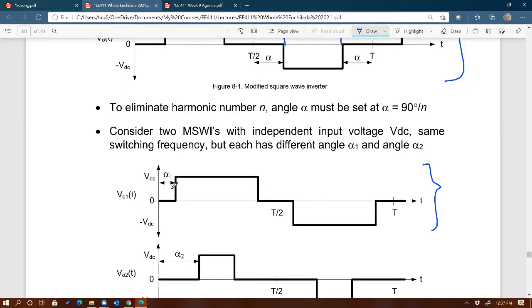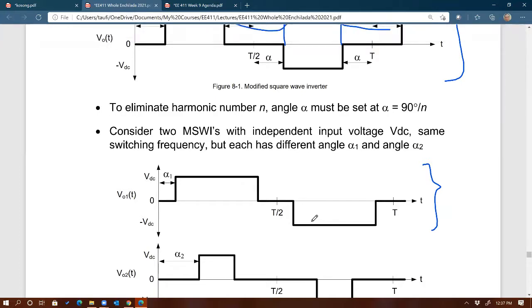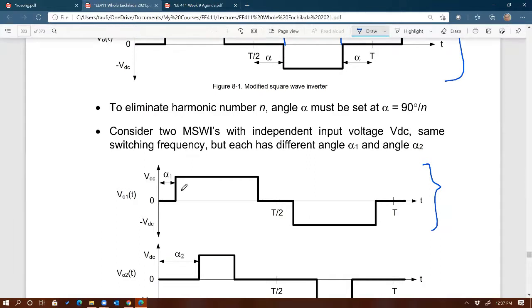Imagine if the applied voltage looks like this, then you have some kind of spinning of the motor shaft that is not smooth, because of this shape. What do you call it? Like cogging, maybe, a torque ripple instead of a voltage ripple. If the voltage is not smooth, you will have a torque ripple.